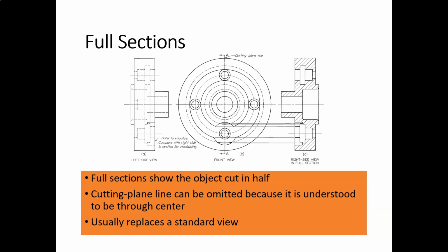It basically means where we view the object in order to see the section view. So the arrows are pointing, in this case, to the left, so that means our eye is going to be somewhere out here, and we're going to be looking to the left to see the cut section. And that's where our section view is right there.